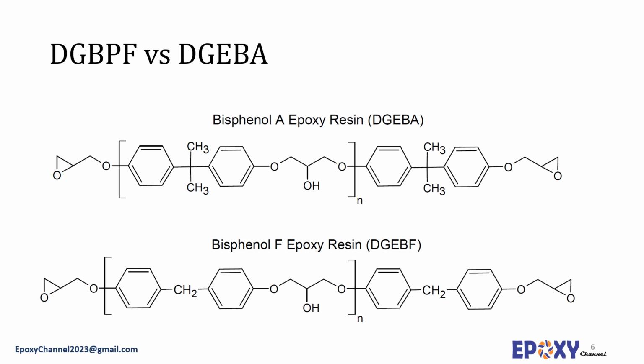If diglycidyl ether bisphenol F resin develops haziness or crystallizes during storage, it can be restored to its original condition by gently warming the container to approximately 170 to 190 Fahrenheit until all visual evidence of crystallization is gone. Upon cooling to normal ambient temperature conditions, the product will regain its original liquid state physical properties. This process can be repeated as necessary.